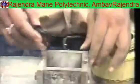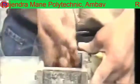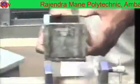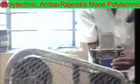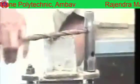A thin film of petroleum jelly is applied to the contact surfaces of the bottom of the mold and its base to avoid water escaping during vibration. After applying the petroleum jelly, fix the mold in the vise and place the assembled mold on the table of the vibration machine along with the vise. Finally, hold it in position by means of suitable clamps on the vibration machine.